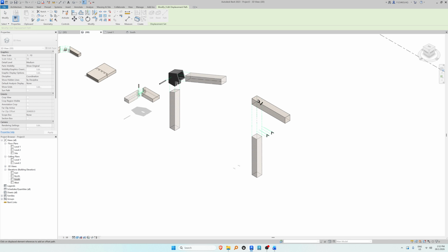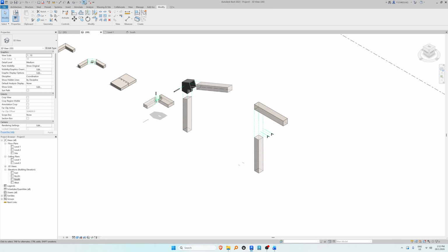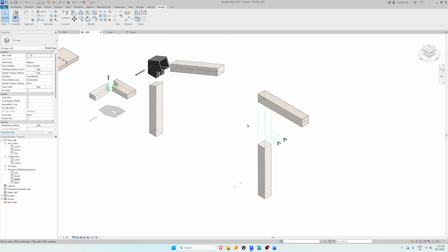This one we can have one more line here that makes it like this. Okay. So these are the lines. So whenever you need to fake a line, you just add in that extra line, make it a reference and make it invisible. So you have this, change it to thicker lines so they look a bit nicer.